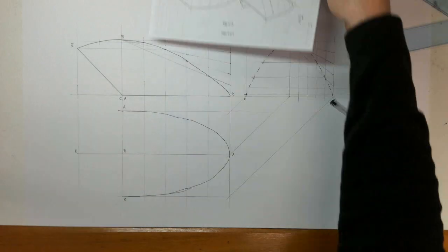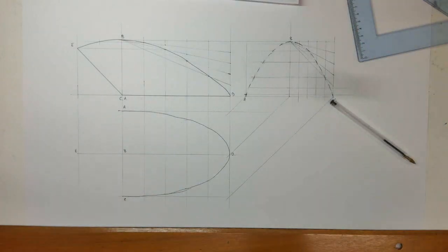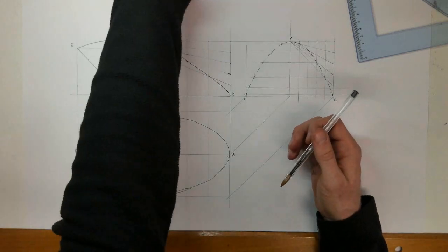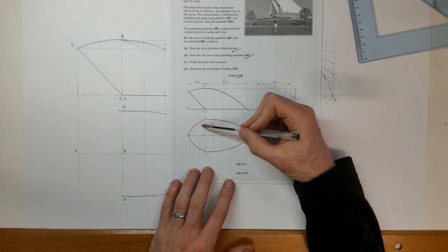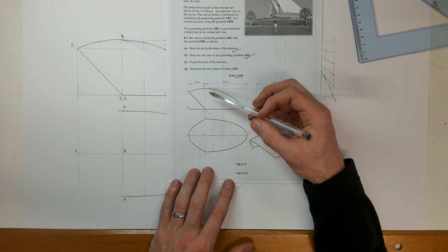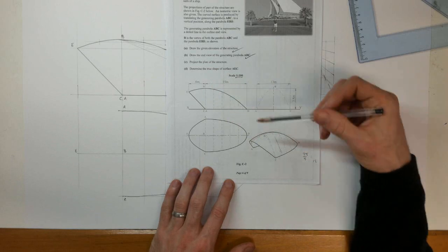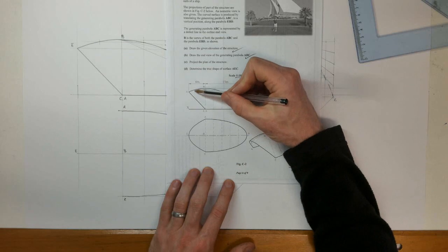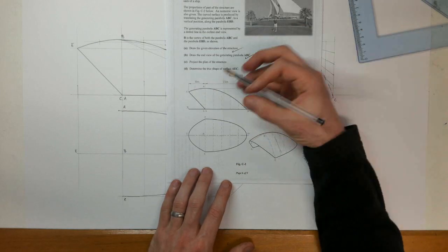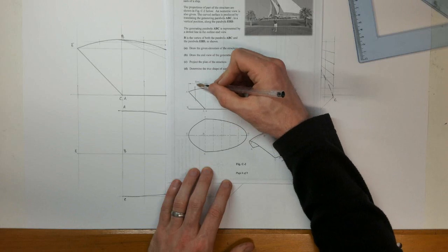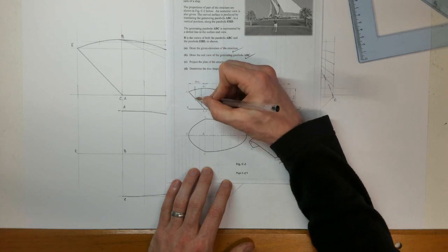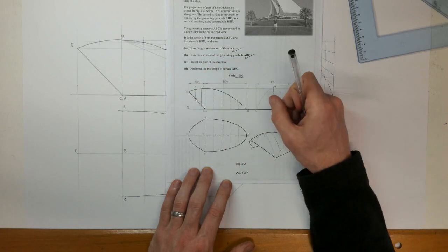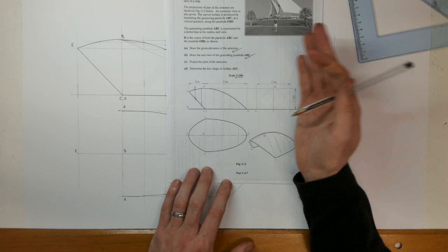We still have this side to do. So for that part, it's going to be narrower. So let me just show here. This is going to be getting narrower and narrower and narrower, right? The heights are actually going to be different to the ones on this side, because as you can see it's cut short. So I'll take a couple of sections here. If I take a section there, that height will be the height that I need to step off, because that's the height of the helix, or the parabola at that point.